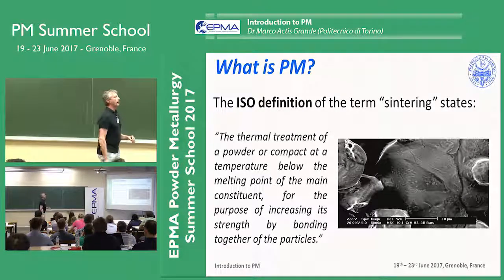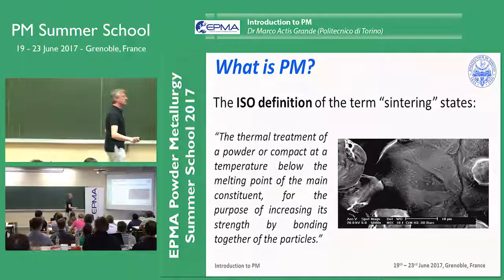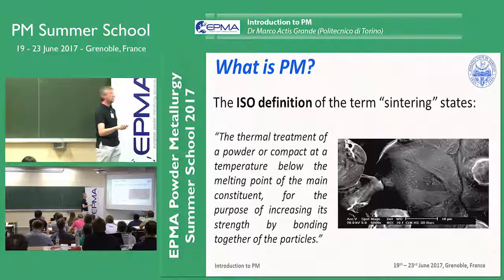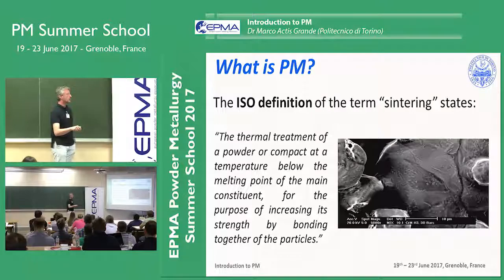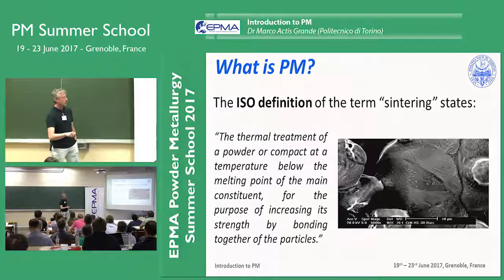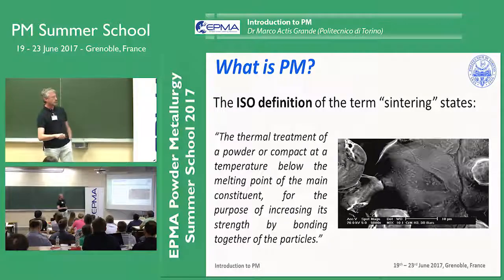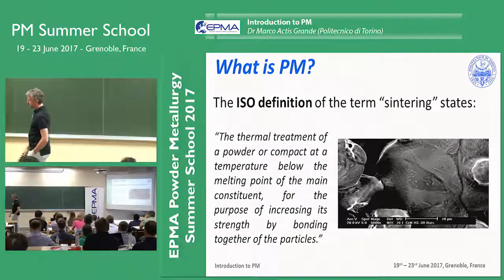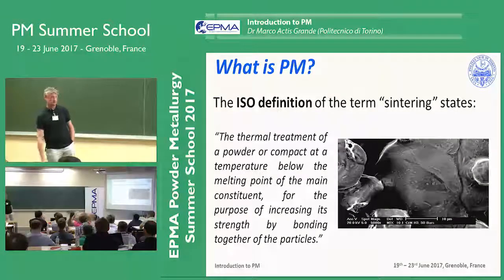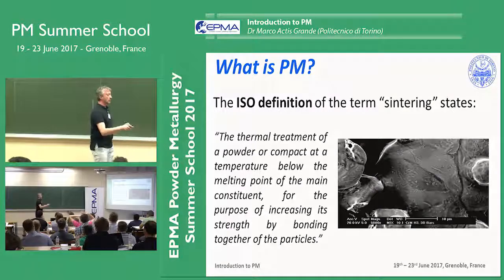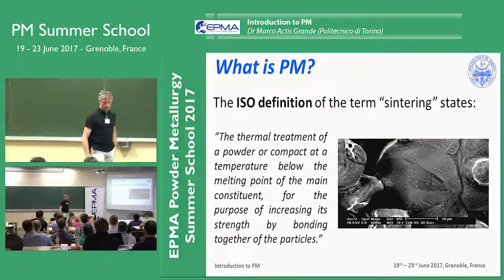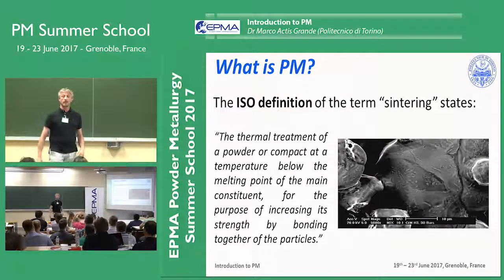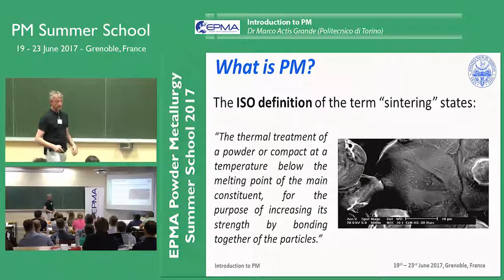If we go for the ISO definition, sintering is referred to as the thermal treatment of a powder or of a compact at a temperature below the melting point of the main constituent for the purpose of increasing its strength by bonding together the particles. So basically this is opening up a set of possibilities, a set of chances that will be well deepened in the sintering presentation, in the fundamentals of sintering, which will be held this afternoon by Professor Bernd